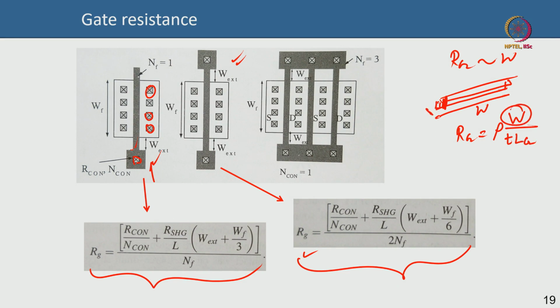So, with higher width the gate resistance goes down, which is very bad for noise and Fmax, and with lower LG the gate resistance also goes down. So, if you go from 65 nanometer to 45 nanometer, because the gate length is reducing, you will get higher and higher gate resistance. Okay. So, that is very important. That is why with higher scale devices your W also has to come down. That is the reason with high frequency millimeter wave devices the W has to be very small.